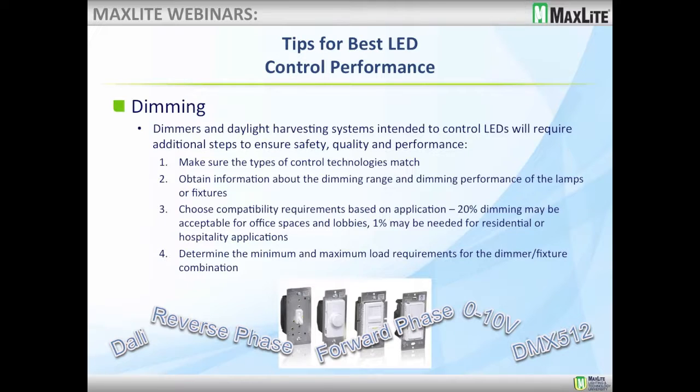and then choose your compatibility requirements based on the application. If you know that you need 1% dimming, you're going to have to maybe spend a little more money and be a little more discerning in your combinations of dimmers and controls. If you can do with 20% dimming, you might be able to offer a much more cost-effective solution.